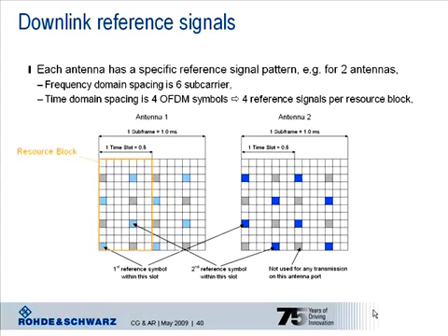LTE uses MIMO technology. 1, 2 or 4 antennas are used for transmission or reception. Depending on the MIMO mode, here spatial multiplexing, different data streams might be transmitted over the antennas. To ensure correct demodulation and decoding at the terminal site, the UE needs to distinguish between the different antennas. This is done with the help of the reference signals.